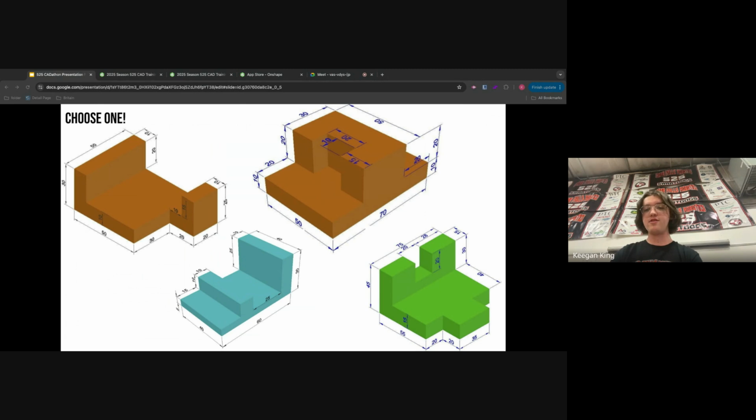I'm going to put the first corner here down on the origin, and then I'm just going to click off. I'm going to type 50 for this bottom measurement, and then I'll hit 70 next. That'll give me my two dimensions. And so right now we have a 50 by 70 rectangle.